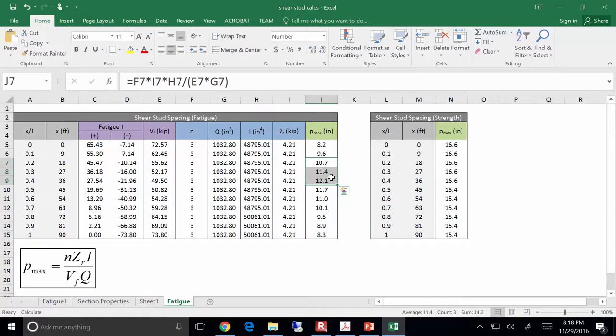A lot of times what you'll find is one of two things with stud spacings. Either on a simple bridge, like a 40-foot bridge, 60-foot bridge, whatever, they'll just use the same stud spacing across the whole span, just to keep it simple. If you're talking, however, about a 160-foot bridge or 200-foot bridge, probably 2 increments of stud spacing. I mean, you could do 3.